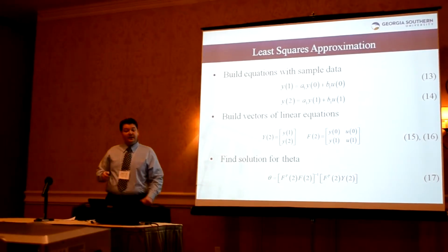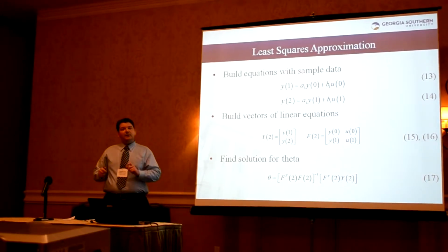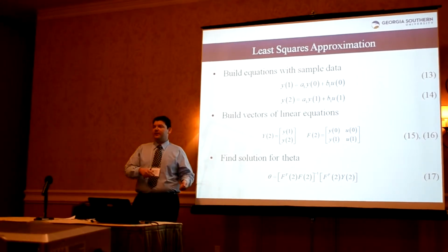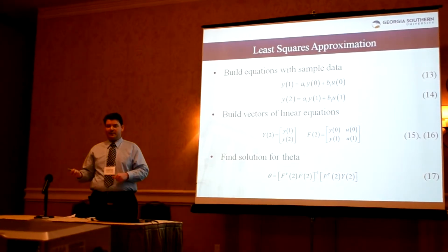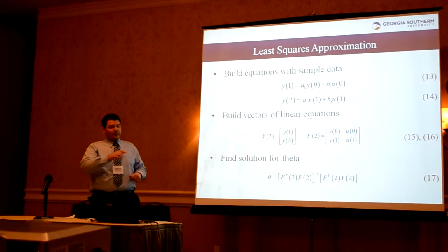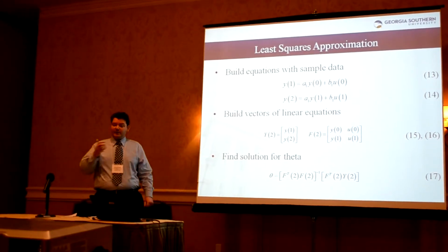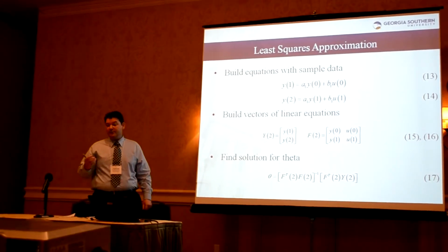So what this does is create a sliding window calculation where for each 3 samples of response data, you can calculate a parameter A1 and B1 to describe the system dynamics. So throughout the range of collected data, you can calculate several versions of A1 and B1.